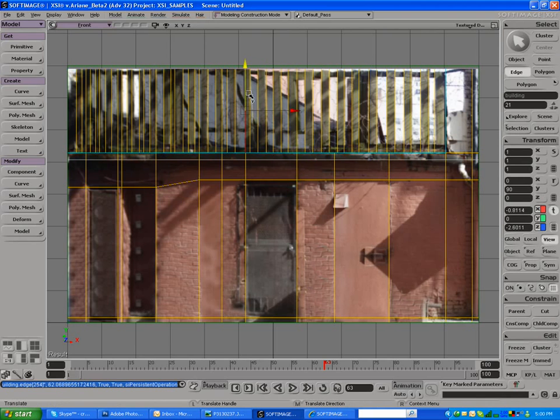So we can just go in and start tweaking stuff as we need to. I'm only moving actually in the x-axis, so we can actually lock these as well. So we can just click on X only, and now whenever we pick on things, I don't have to worry about going in and picking the wrong axis. It's just again a little thing to make my life a little bit easier and a little bit faster.